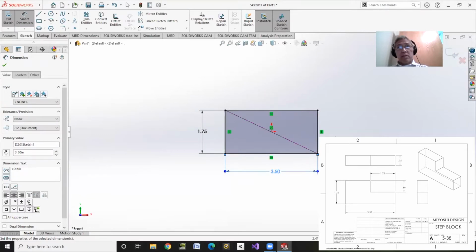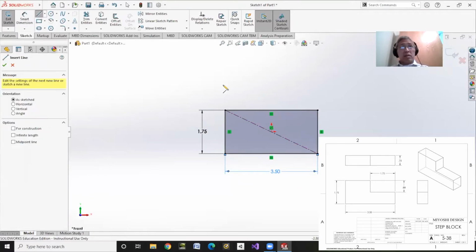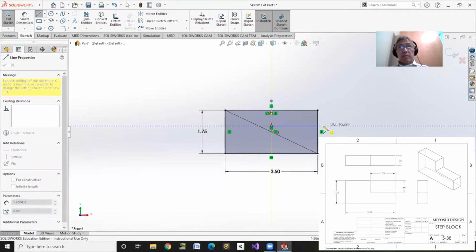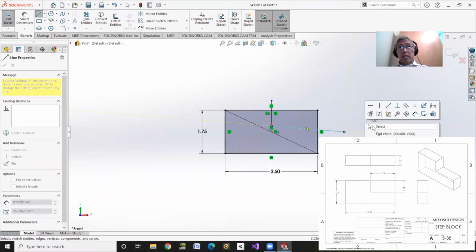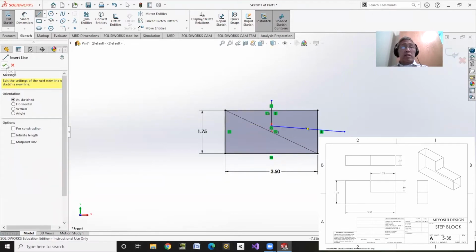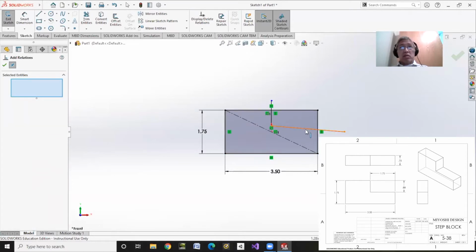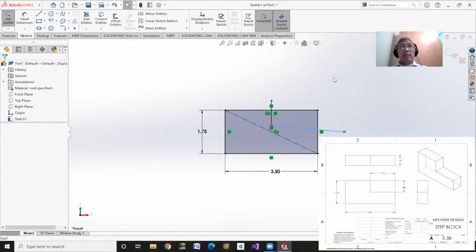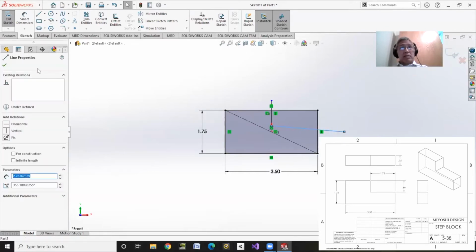Okay, now there's a notch out of here, so I'm going to make a notch. What you can do is just make a little line. I'm just going to make the line outside of my box. And notice it can be horizontal, vertical. Maybe I'll make this guy not quite horizontal, and then I'll go in chain, and then I'll even do one last thing in add relation. Now this guy here is not vertical or horizontal, so I'm just going to grab it and make it horizontal. The other thing you can do, you don't even have to add relation. If you just have a single thing, you can just select it, and right over here, you can make the property be horizontal.